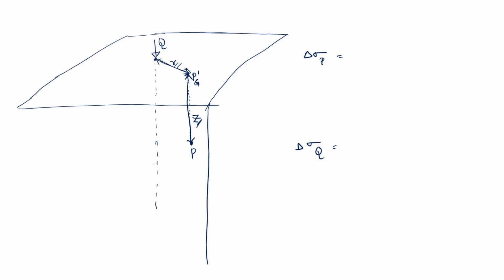Now I'll write the formula: 3 by 2 pi into 1 by (1 plus (r by z) square) whole power 5 by 2, into Q by z square. See here, P and Q are existing exactly below the load, somewhere here and somewhere here.